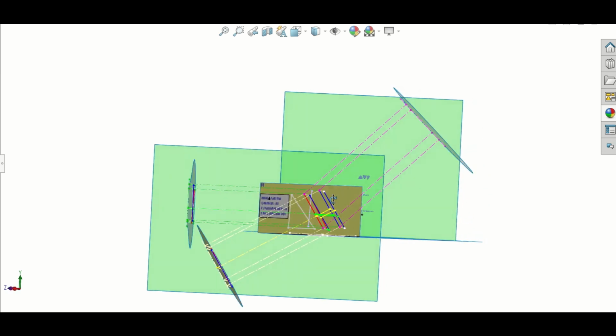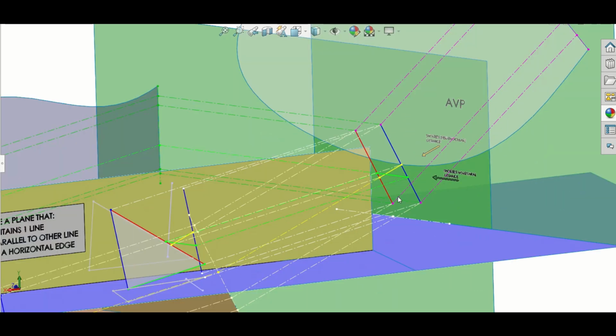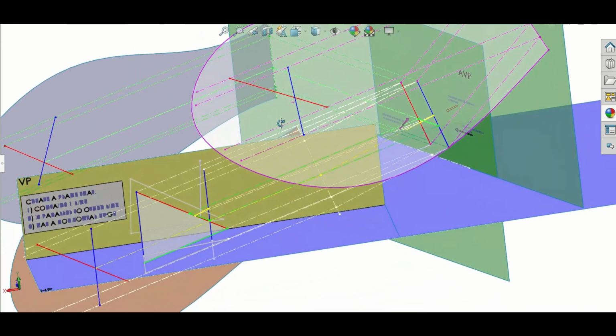I'll flick through it quickly, I'll draw it on paper. So this view here, showing them as parallel, we pitch up at an angle of 45 degrees and view, and we put our x1, y1 line in. We project out through those views and we get each line appearing up here, and they're appearing in a different manner again this time.